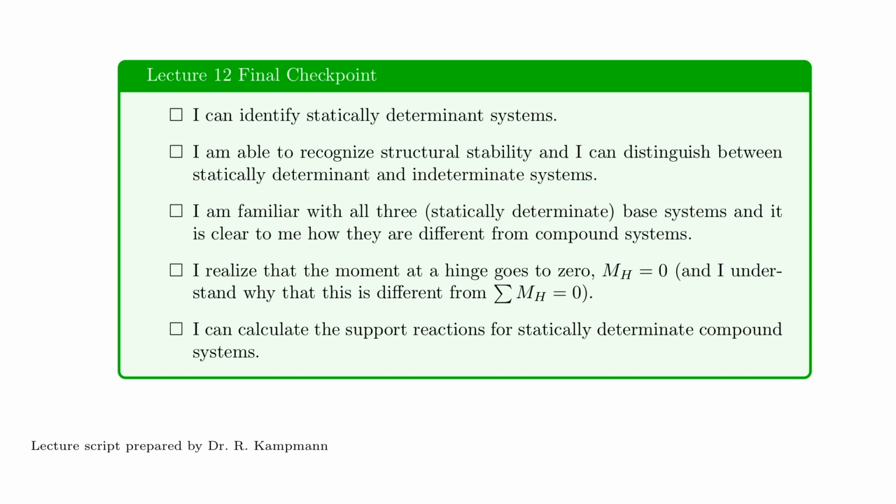And the first thing that we, of course, talked about was the statically determinate systems and what makes a system really statically determinate. So we can now identify these systems so that we can also understand what stability is, and in specific terms structural stability, so that you can distinguish the determinate and indeterminate systems. So I hope you remember that you don't have to calculate any forces in statically indeterminate systems, but you have to be able to identify statically indeterminate systems, and you have to know the degree of indeterminacy. So you need to understand that.